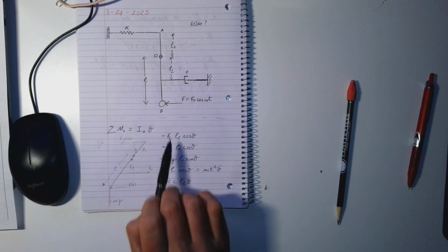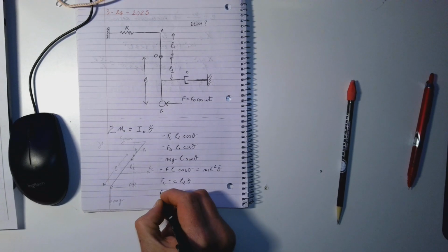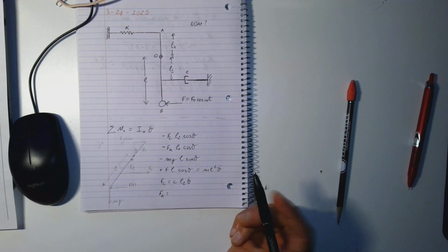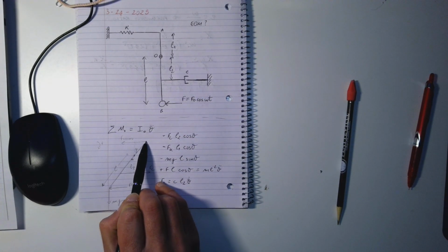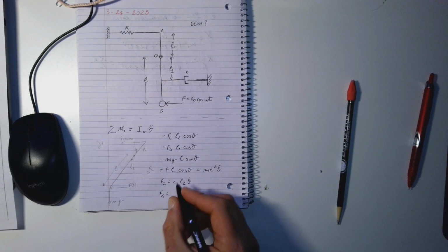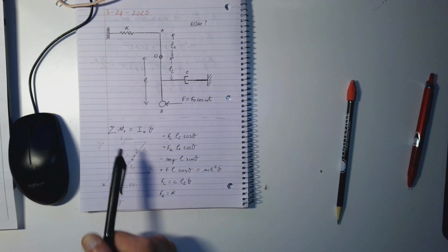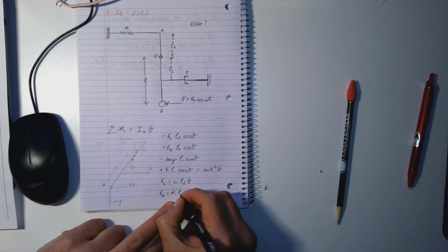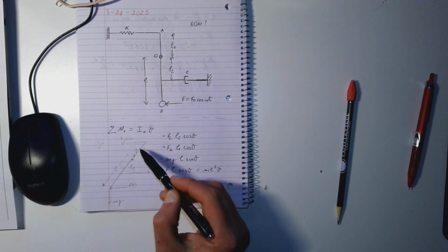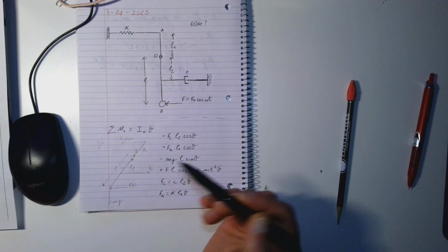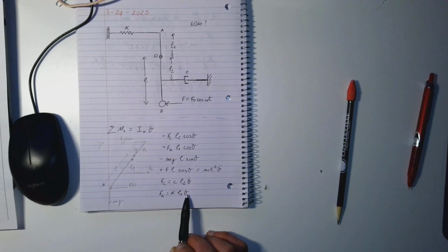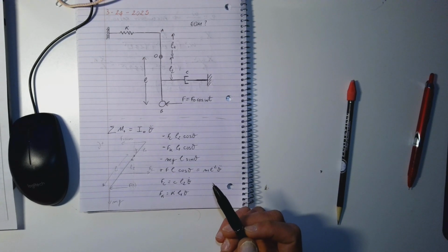And then we have to do the same with this term Fk. In this case we don't need to look at the velocity, we need to look simply at the position. So we need to look at the position of this point here, again with respect to the geometric parameters of the body. So we have k, which is the constant of the spring, times L1 times theta. So we're looking at this position here, L1 times sine of theta, but since it's a small angle, we consider only L1 times theta. Makes sense?